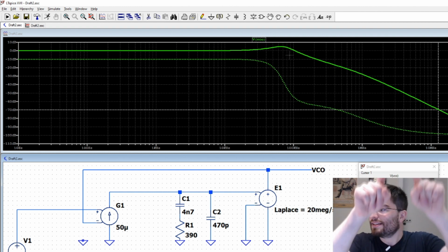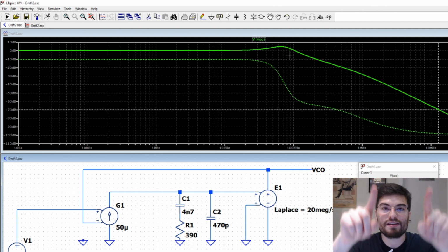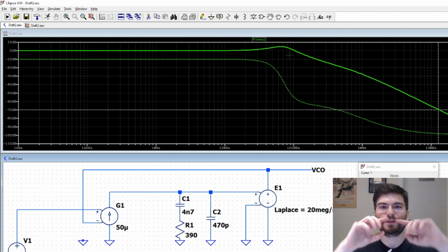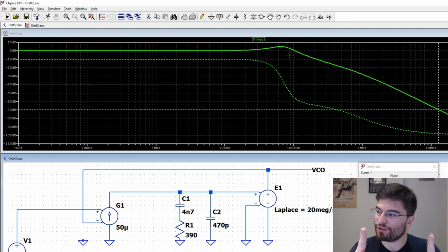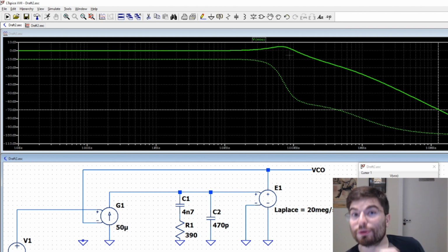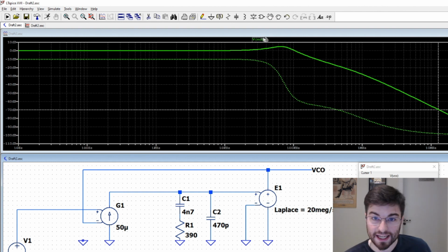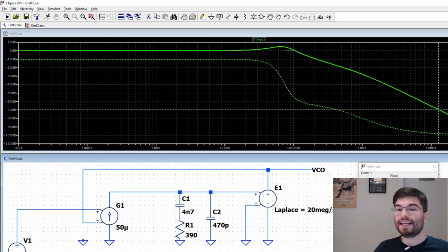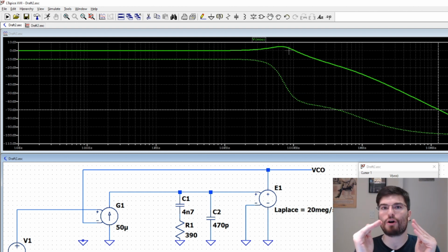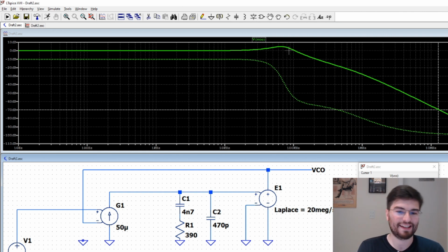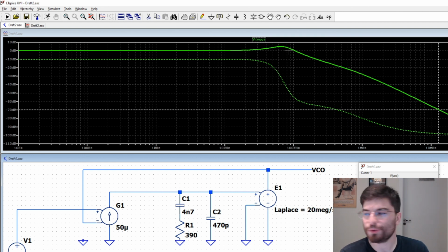Okay, and you can see that this peak here, guys, is what generates the phase noise characteristic of a PLL. You can see in the output of the PLL, in the last video I posted, the circuit working. You can see clearly the response of the PLL doing a shape with a bump. The bump is this peak here in the closed loop response, guys. Because actually this response here will shape the phase noise and the relation of phase noise from the VCO and from the reference. Yeah? So guys, I hope you enjoyed this video.